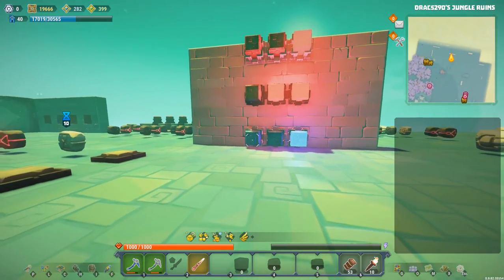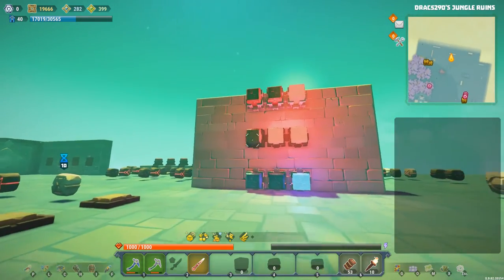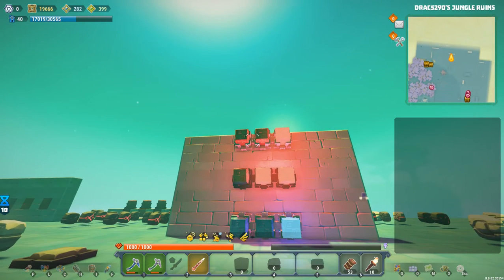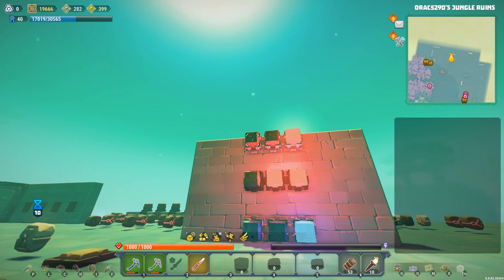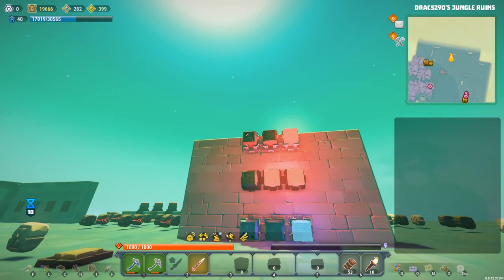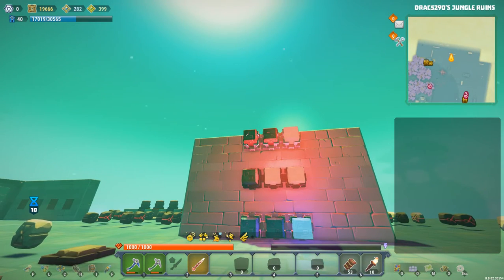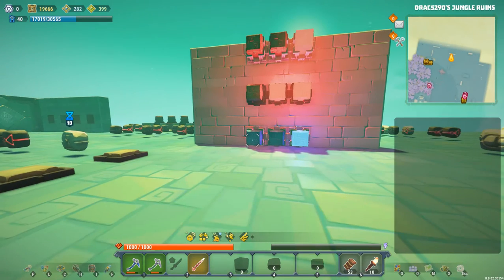And once again, with the third light here, the third light is an exclusive OR of this guy and this guy, so the third light in the counter and the second light in the sequencer. Now, that does mean that we're having a third light in the sequencer that we're not using, but that is okay, because that means that there's actually a bit of time where one of these two lights isn't on, and that's a good thing. Adding extra stuff into this that doesn't actually do anything to the output just adds time delay to the output, so it actually makes it even more random, or at least slightly more random.